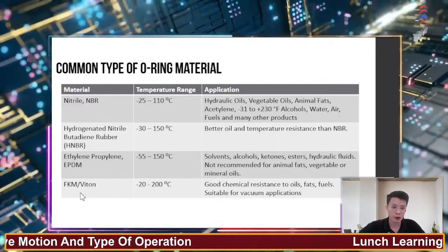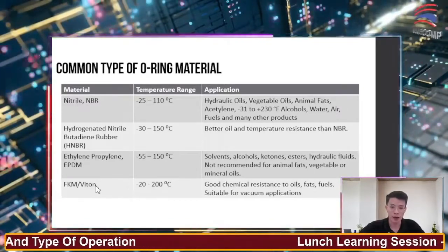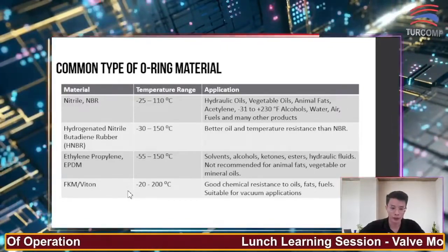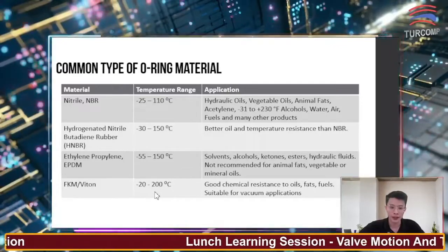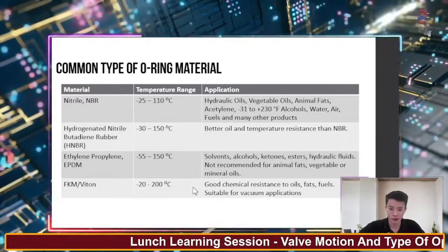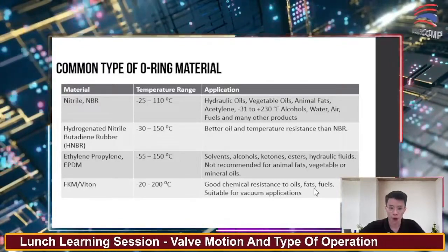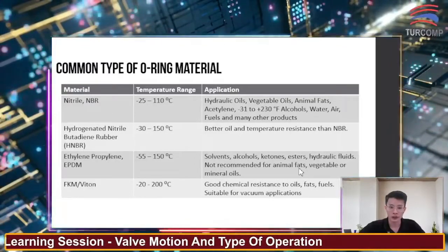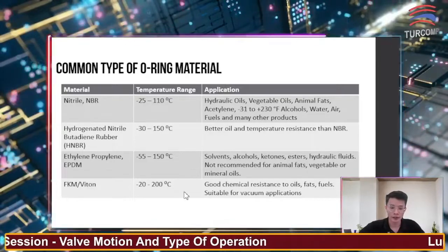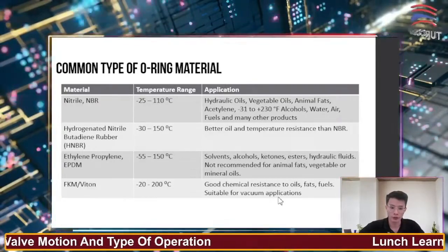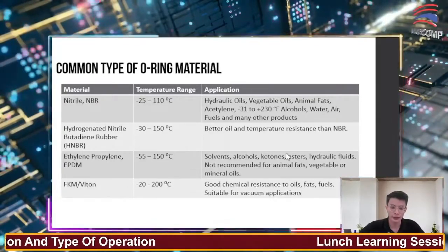The last common type is FKM, or we call it Viton. The temperature range is -20 to 200 degrees Celsius, and it has good chemical resistance to oil, fats, and fuel. For this last type, FKM or Viton, it is suitable even for vacuum applications.